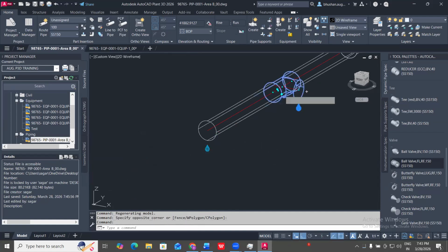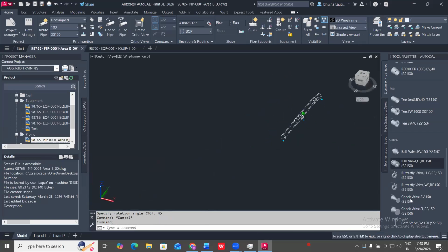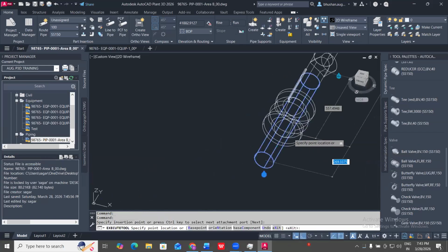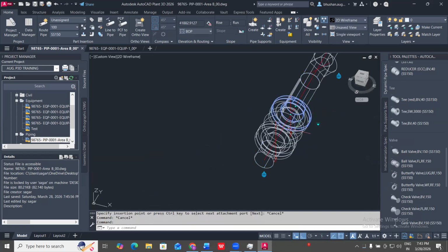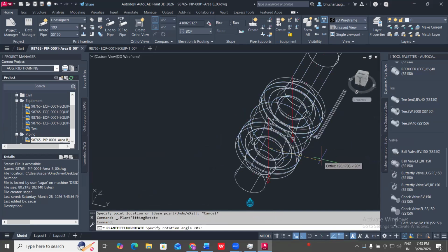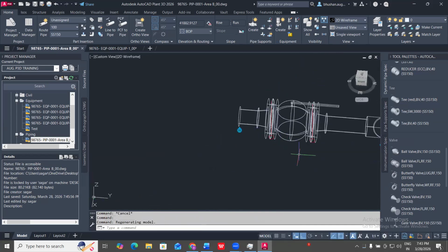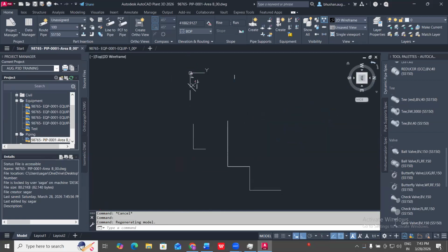Also for the T I can do that. So with 45 degrees, it would add a 45-degree automatically. I can do the same for the valves also. The rotation option is there; continuation grips have been given to the valves. Those things are already given in Plant 3D whenever you are adding a component in your PipeSpec. Okay.